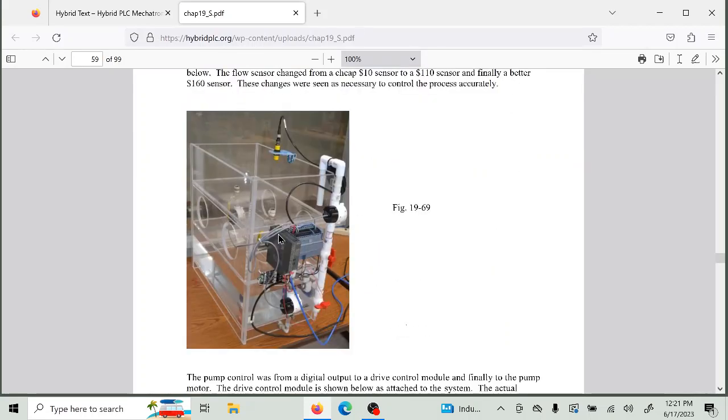Those are some early pictures. These are some later pictures, and they're being modified again. But basically, at this point in time, we're set up with some pretty good sensors. The tank over tank, we've modified some of these sensors two or three or four times. We started with a level control that was much simpler than this, but this one worked very, very well, and this one's the one we settled on. So cheap isn't always the best. These are not cheap. These are like $200 a piece. But the level controller that we had before this did not work.